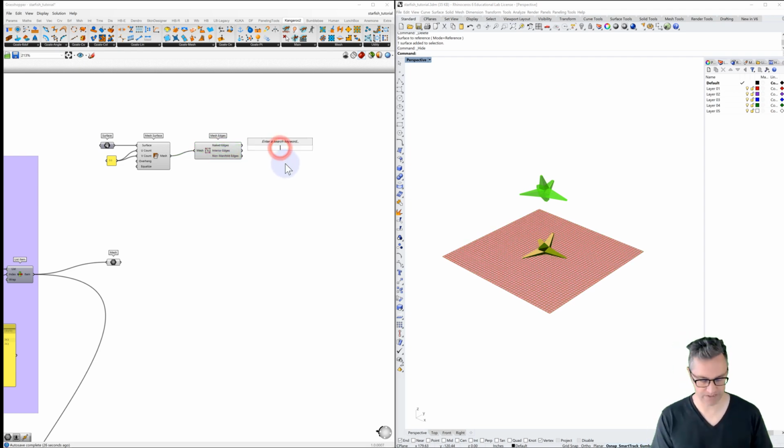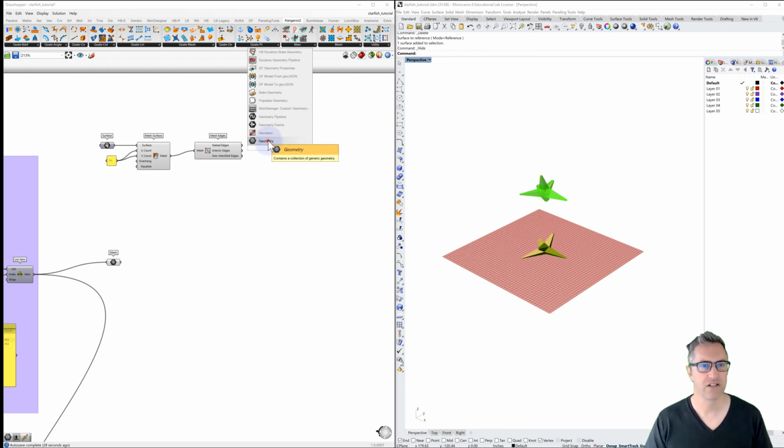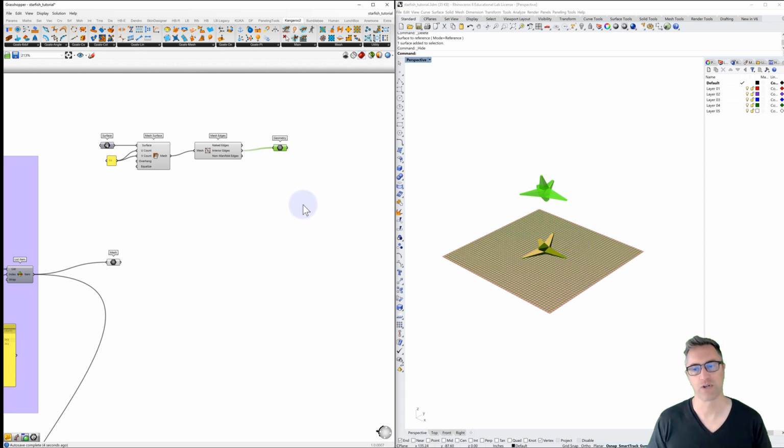Let's try geometry. So naked edges, as we plug this in, are giving us just the edges all the way around. The interior edges are giving us all of the lines that are in the middle. So we're going to use these lines as the springs of the bouncy solver for the next simulation. So now we have access to those, and that's good.